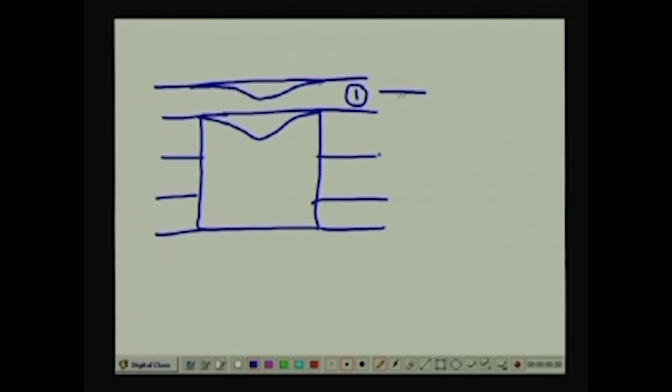Now, if in addition we have a large horizontal pressure acting on this particular slab, then you can easily notice that the problem of sagging is going to get accentuated, and this may become so severe that the slab near the top of the tunnel is going to fail.